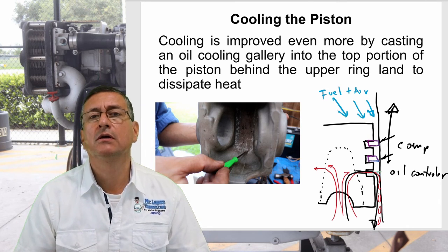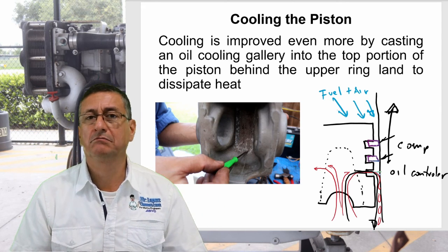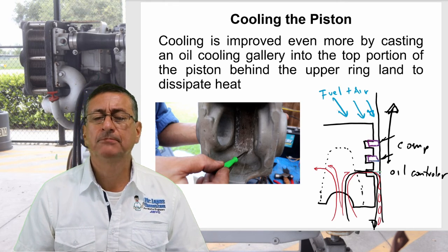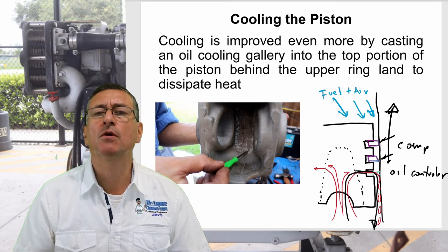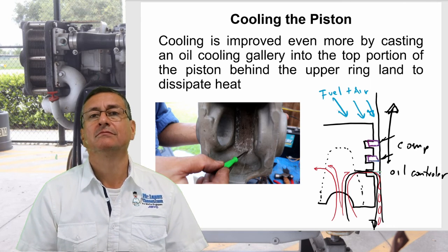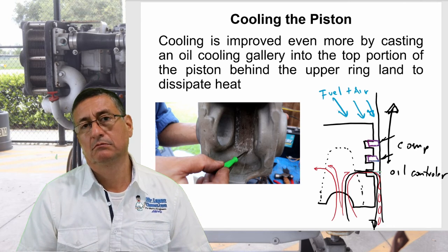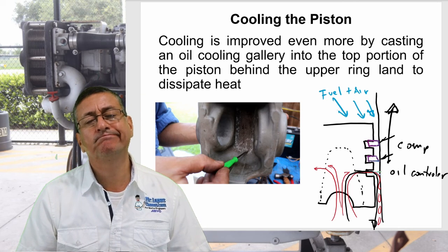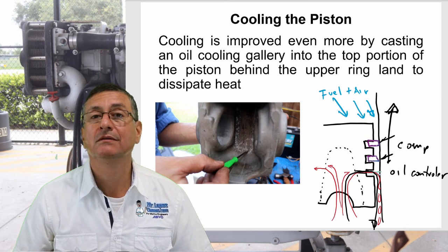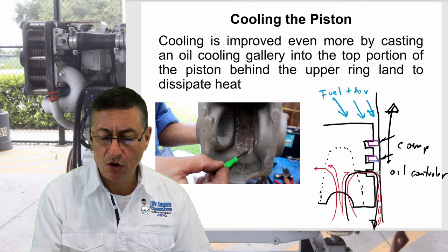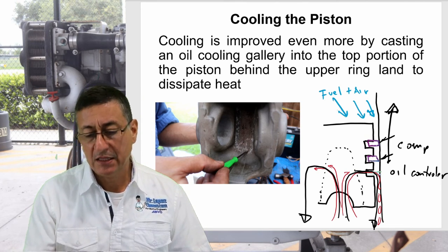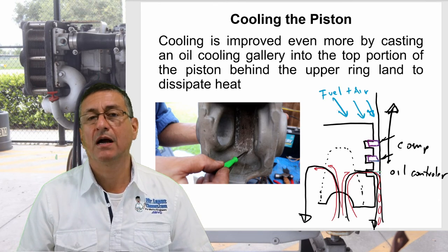If you have blue smoke, the majority of the technicians say, oh, this is a problem with the piston rings. No. What is the symptom when you have a problem with the piston rings? Yes, low compression. Oil in the combustion chamber? No, because we have the third piston ring, the oil controller, that allows the oil to enter here and return into the oil pan.